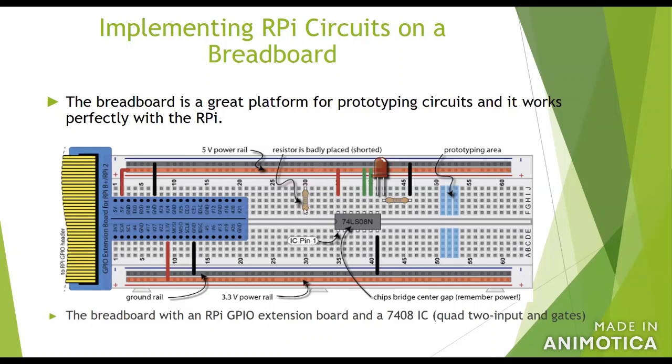Okay, and on this breadboard, you see we have these two lines. These two lines are used for power. That means all the holes in this line are all connected together. Okay, so if you plug something here, and you have two wires, this wire and this wire, these two wires are connected together, because for a breadboard, all these holes are connected together.